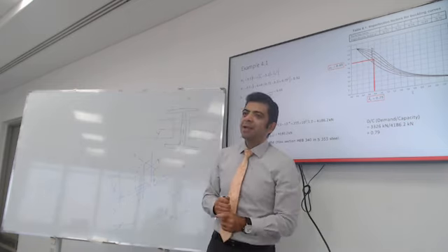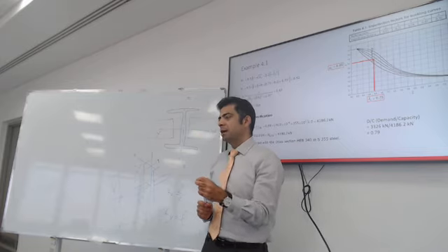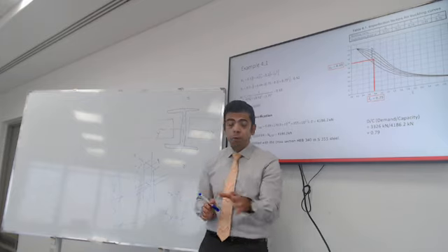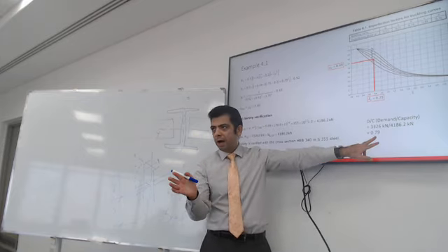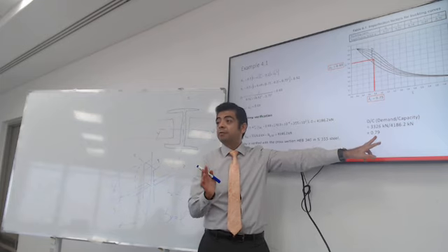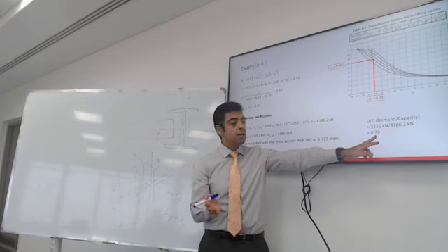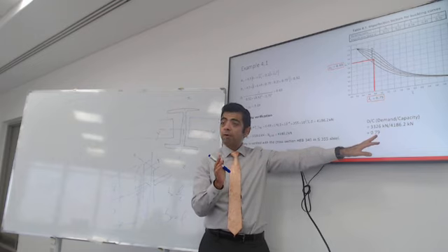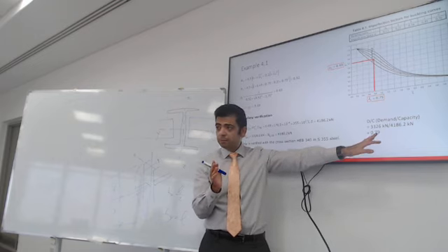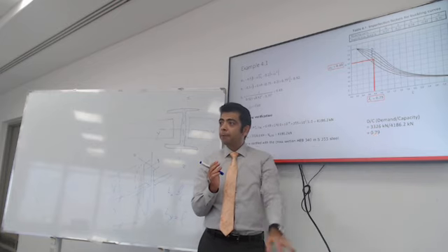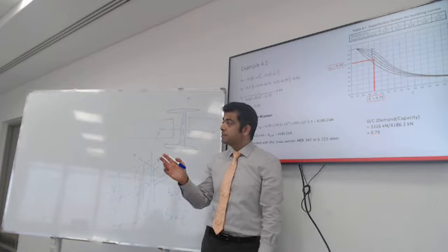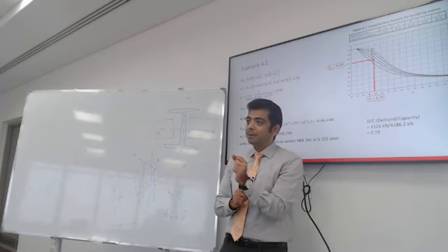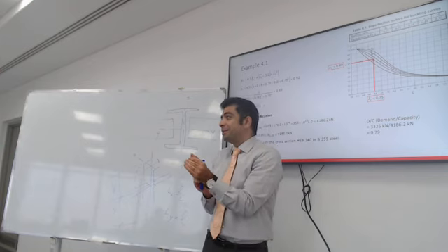Yes. The reason why I like this discussion very much is because the client, when you discuss with anyone you're working for, they don't like this to be like 0.5 or 0.4. This is a waste of material. This is going to be very expensive. That's true. So they like to see north of 0.8. The question is, how far do you go? Do you want it to be 1? No. Why? 1 is most economic. Do you want to design for 1? No. You'll feel uncomfortable? It's too close to the edge?